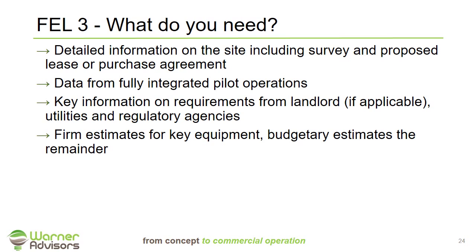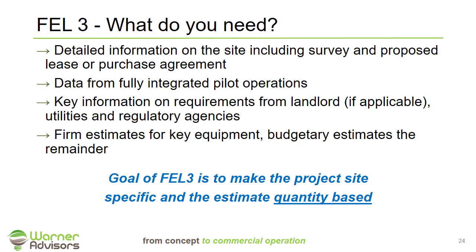This will help you generate firm estimates for key equipment and get budgetary estimates for the remainder. Just remember, the goal of FEL3 is to make enough engineering detail to make the project site specific and to be able to estimate quantities of piping, concrete, and other materials to be able to generate a much more accurate